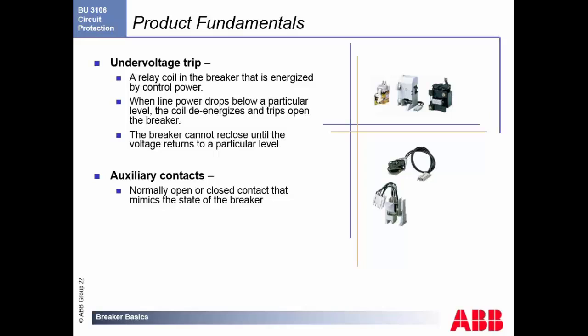So what this allows you to do is set a level for monitoring the voltage coming into our breaker. And when it dips below that, this shunt will recognize it and open the breaker automatically. We have auxiliary contacts so that there are ways to use switches to disconnect the breaker or open the breaker without actually going to the breaker. Again, a very nice safety feature.